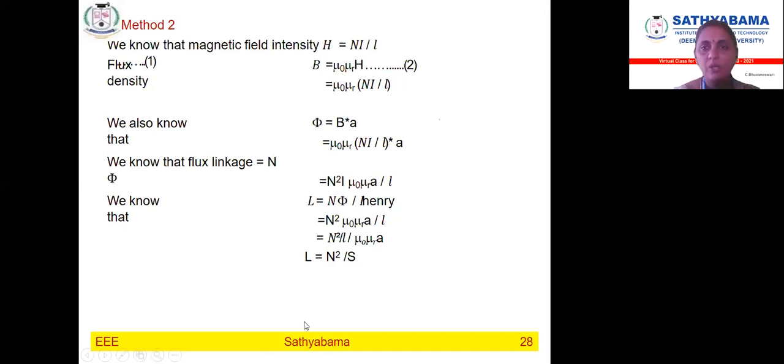Today we have discussed what induced EMF is, and the major classification of induced EMF: the statically induced EMF and the dynamically induced EMF, and again the classification into self-induced EMF and mutually induced EMF. In this we have read up to self-induced EMF. Expressions for self-induced EMF we have done, and expressions for self-inductance: L is equal to N phi by I, or L is equal to N square by S. Any doubt here, you can just let me know.